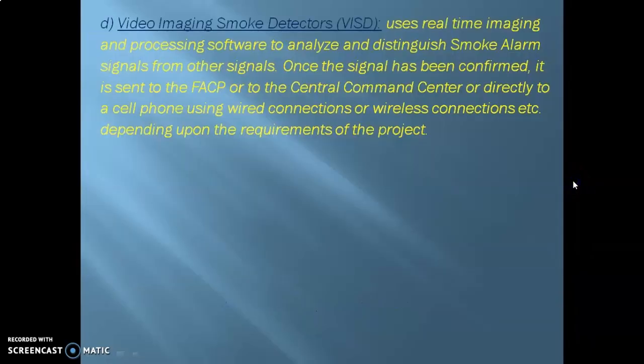Alright, so next, the fourth type of smoke detector that we have is the video imaging type of smoke detector, or the VISD. What this means is that it uses real-time imaging via cameras, and specially developed processing software to analyze and distinguish between smoke alarm signals and other signals or conditions that might exist within the protected premises. Again, this is basically used for large areas, and it is quite accurate to quite an extent.